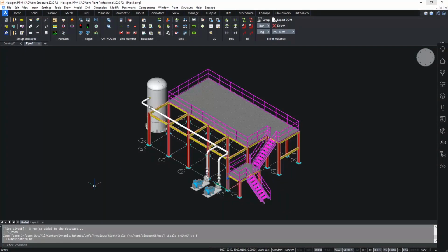I'm done with it. The final thing then to do is run the isometric, and that's very easy. There's two buttons here. You can either run Isogen batch to export multiple line numbers. If you have a more complex model with more lines, you can run each line in a single run, or just a single isometric, which is what I'm going to do using the Isogen out function.